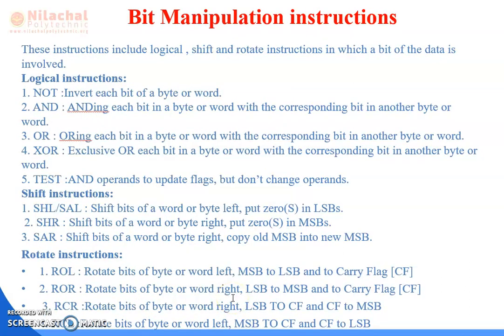Next, bit manipulation instruction. These instructions include logical, shift and rotate instruction in which a bit of the data is involved. Then logical instruction, first one is NOT, that means invert each bit of a byte or word. Next AND, that means ANDing each bit in a byte or word with the corresponding bit in another byte or word.